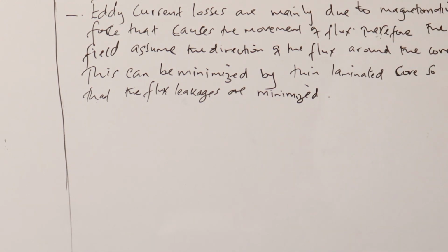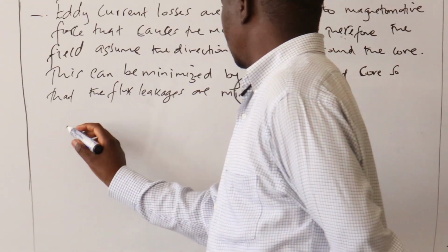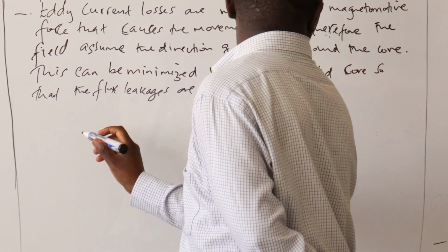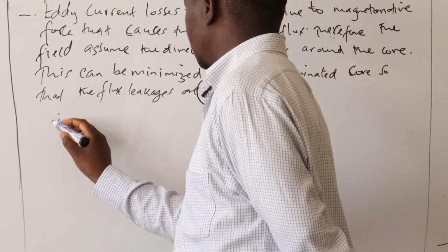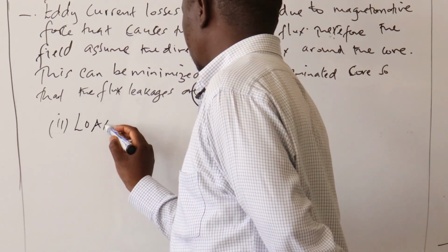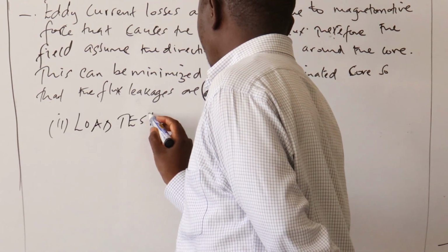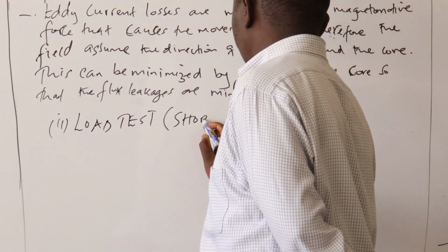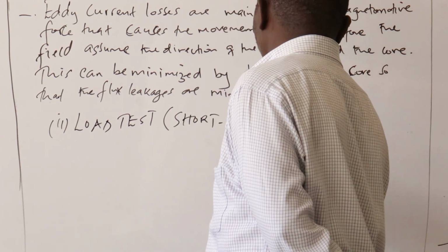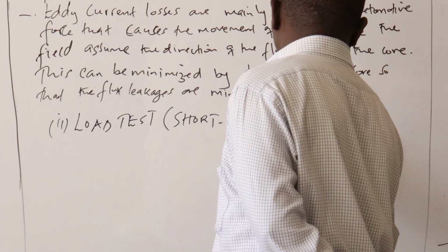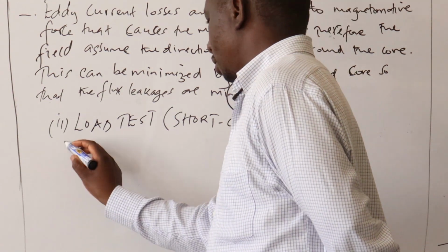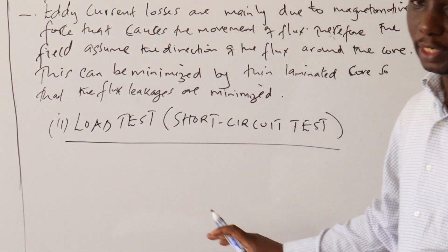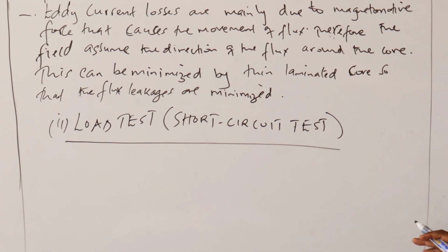So from there we shall be able to do the copper tests, the load tests, whatever as the short circuit test. With this one, we shall have the same diagram, but the secondary terminals will be short-circuited.